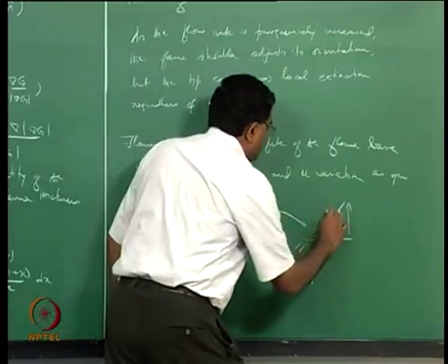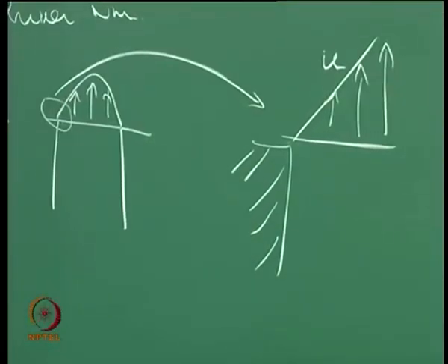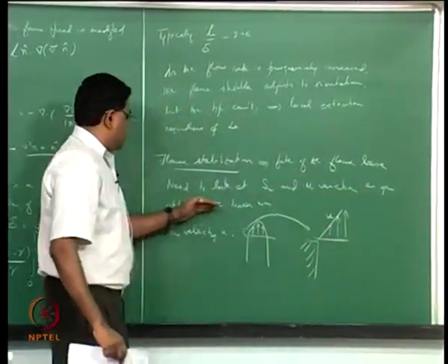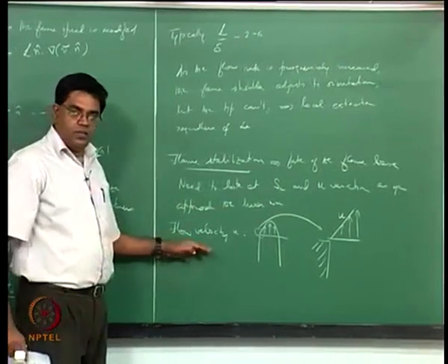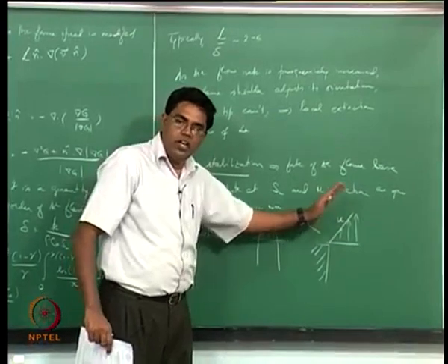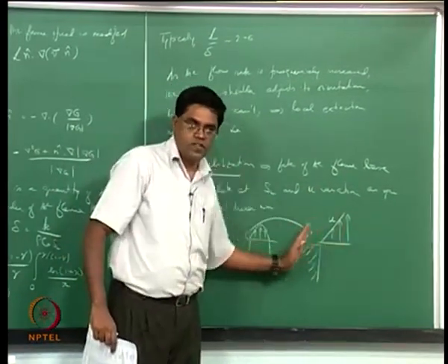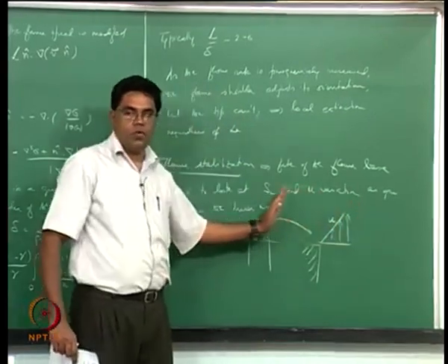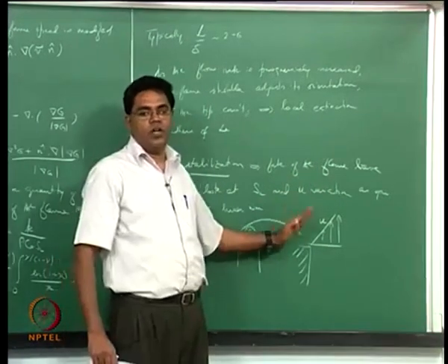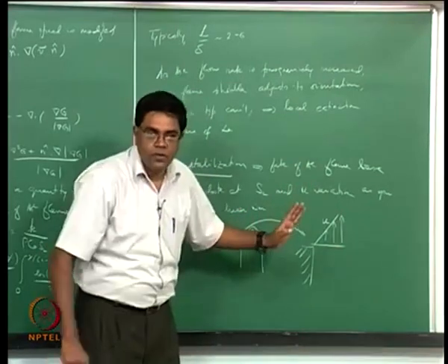That's your U. So when we said that we wanted to look at the flame speed and the flow velocity variation as you approach the burner rim, we picked the flow velocity because it is always going to be somewhat linearly increasing from the rim inwards towards the center of the tube. So that is more like a monotonic variation. You increase the flow speed, the slope is going to increase. If you decrease the flow speed, the slope is going to decrease, that's all.